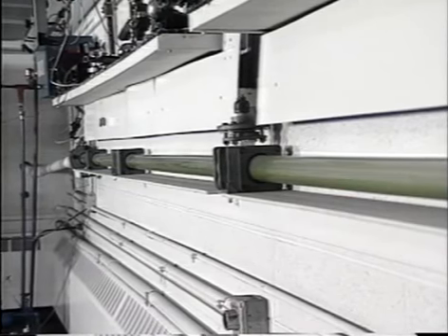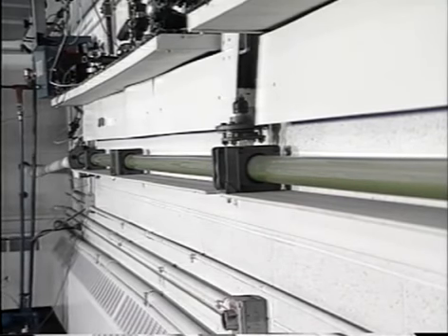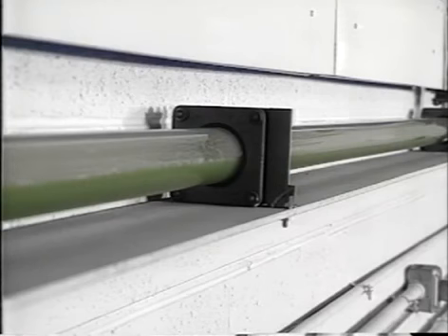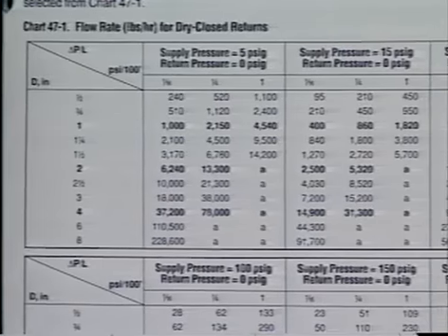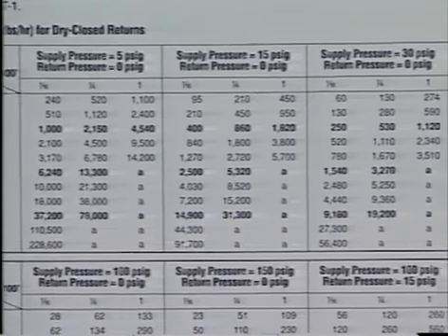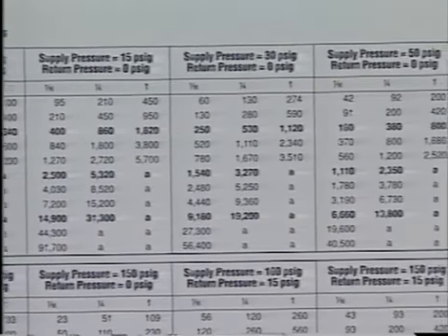Further increasing the airflow causes the waves to block off more of the cross-section of the piping until a seal is formed, completely closing off the pipe. A slug of condensate is accelerated downstream by the pressure differential, becoming a piston that gains in mass and velocity as it travels. The proper sizing and pitching of condensate lines are the only means of guarding against this type of problem.